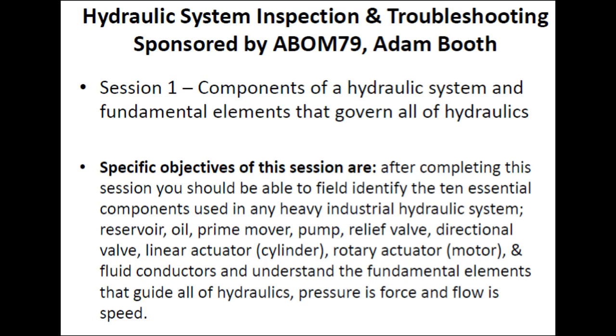So in this particular session, components of hydraulic systems and fundamental elements that govern all of hydraulics, after completing this session, you should be able to field identify the 10 essential components used in heavy industrial hydraulic systems: reservoir, oil, prime mover, pump, relief valve, directional valve, linear actuator, which is a cylinder, a rotary actuator, which is a motor, and fluid conductors like your tubes, hoses, fittings, things like that. And understand the fundamental elements that guide all of hydraulics.